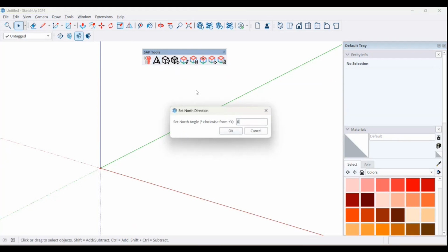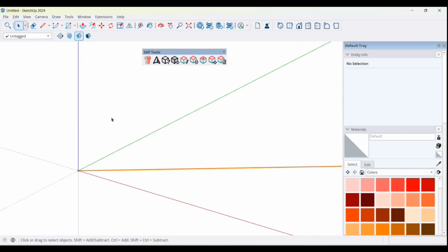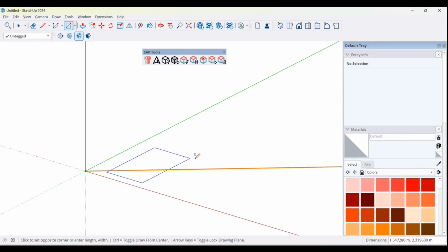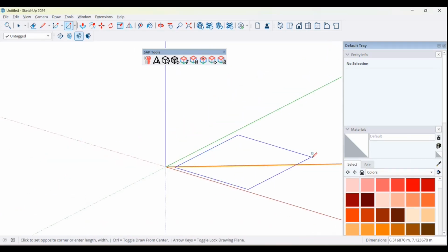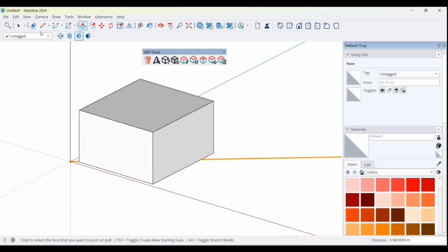So if you've got a site like a housing development with houses at all different angles, you can handle that quite easily. Just key in a north bearing and that displays in SketchUp. Get that all set up nice and simple, and then all you have to do now is start drawing your dwelling. So you might have something a little bit like this. Let's just draw a really simple house shape and apply a pitched roof.